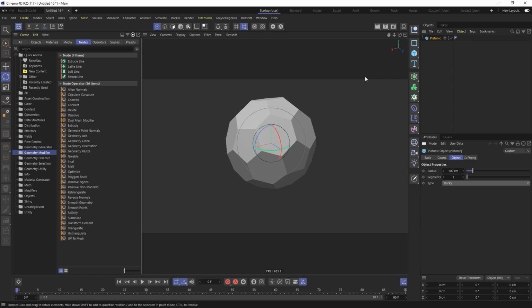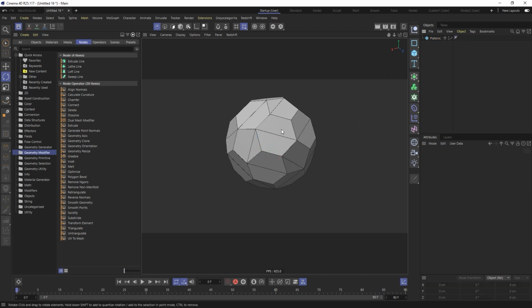one of my favorites. Hitting NB, we can see on the edges that even though each of these flat faces is 5 or 6 sides, we can only display quads or triangles. So there's going to be these subdivisions. That creates a problem if you're going to do some sort of parametric modeling, or maybe you want to clone onto these and clone onto the center point or something like that.